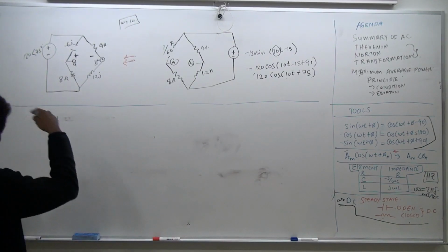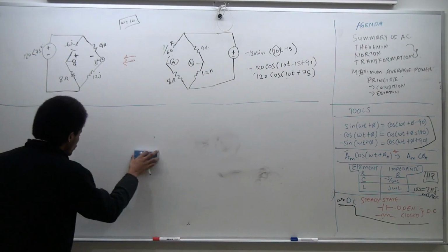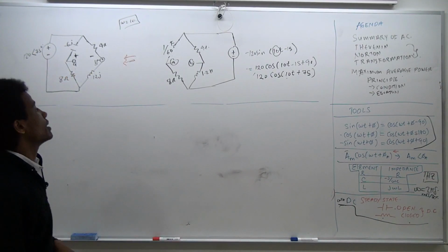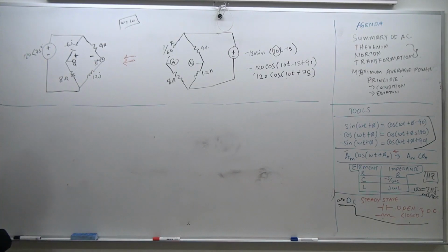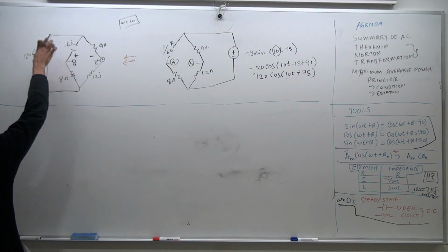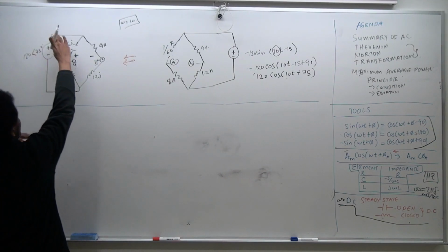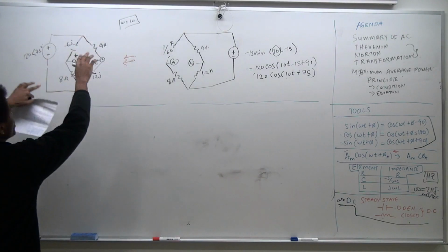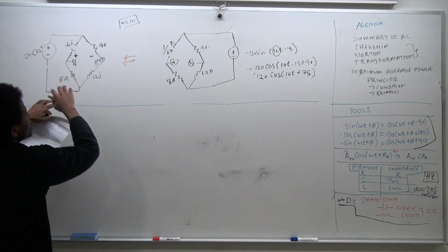So applying what we just discussed, how would we find the Thevenin equivalent as seen from terminals A and B? That's the question I'm asking. I just gave you the information, so tell me what I would do to this circuit. Short what? Yes, I have to short the voltage source, because we just discussed that. If this was not a voltage source but indeed a current source, what would we have to do? We have to open-circuit it. Meaning we would just let go of it, with nothing connecting across. But in this case, we were told to short it.